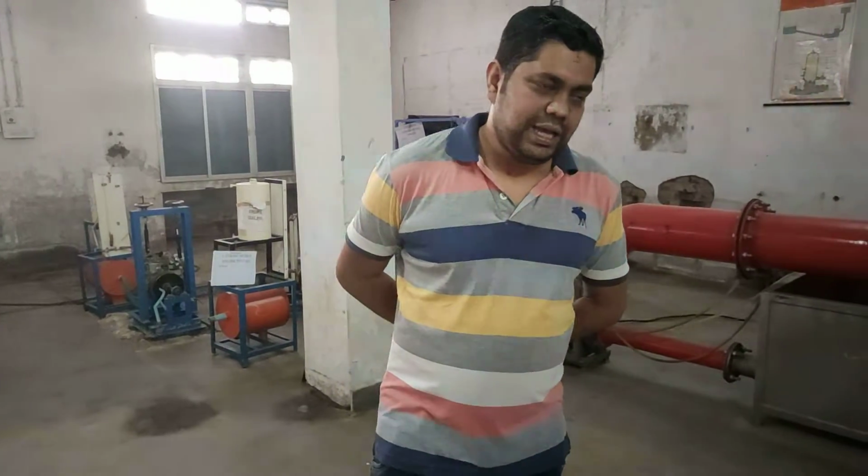Where are turbines used? Turbines are of different types: steam turbines, gas turbines, and hydraulic turbines. Basically we are studying hydraulic turbines. Hydraulic turbines are used in dams and reservoirs, where a high head is required. According to the head, there are different types of turbines: medium head, low head and high head. The impulse turbine is a high head turbine, so we require a high head here.